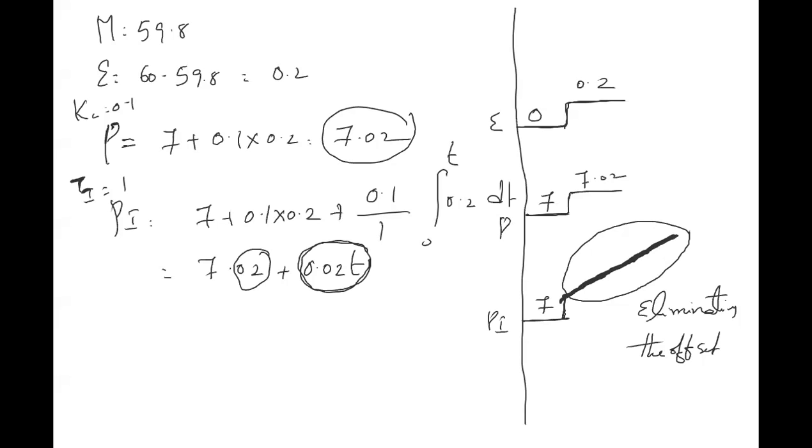So you are continuously closing the valve. At one point of time, you will overshoot 60, that means you will see 60.1. When you see 60.1, suddenly you stop closing and start opening. As you slowly open, it will go below 60, maybe 59.9. Then you will slowly open, slowly close, slowly open, slowly close. This kind of oscillatory behavior will be there until you leave your hand on the control valve when you see a temperature of 60 degrees. Are you understanding my explanation?